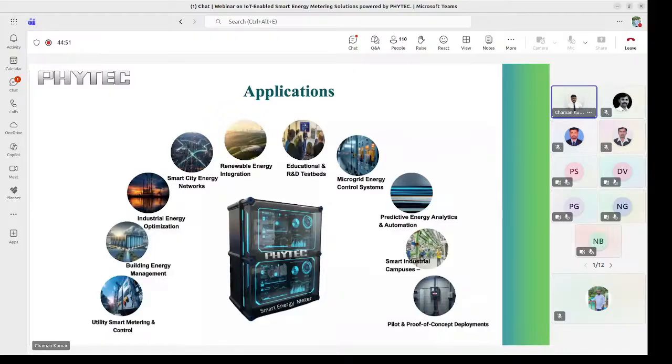Now if you see the architecture, one part is the data model. In data modeling, we can model the data. COSEM is also there. COSEM is nothing but the Companion Specification for Energy Metering. Depending on the country or state, the COSEM protocol is different, but DLMS is the same internationally. Depending on the country and tariff rates, COSEM differs. In COSEM, to model the data there are OBIS codes, object identification codes. You can consider this data model as a dictionary that defines what data is available.